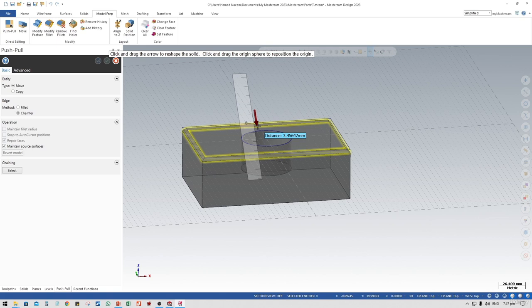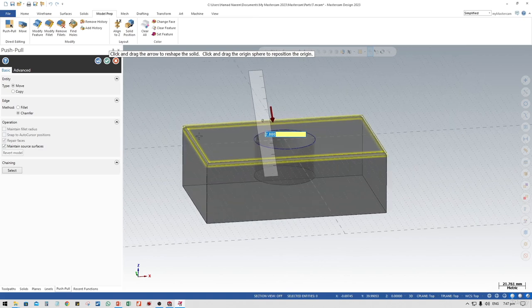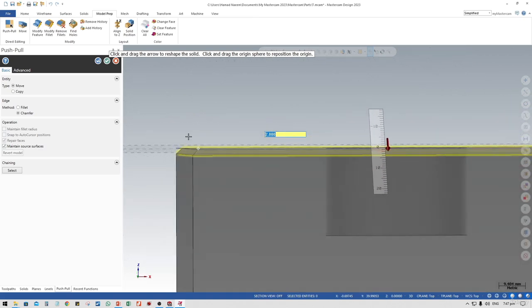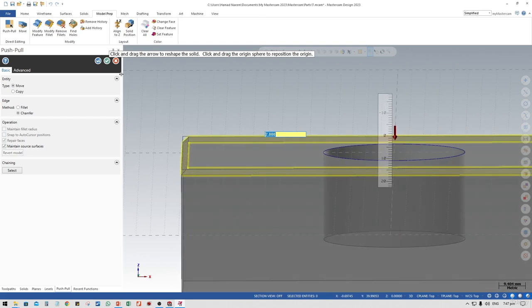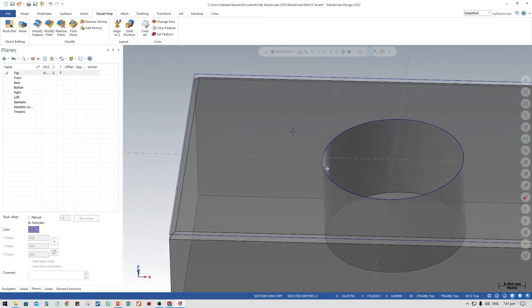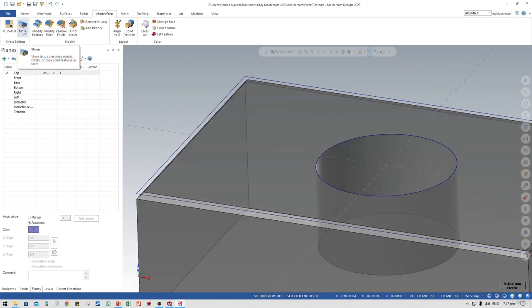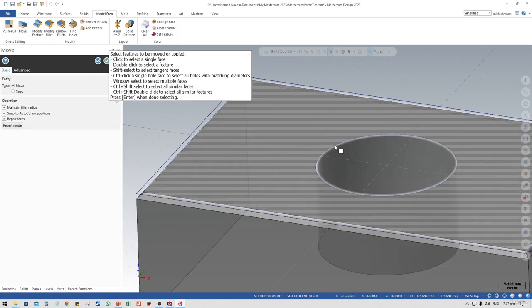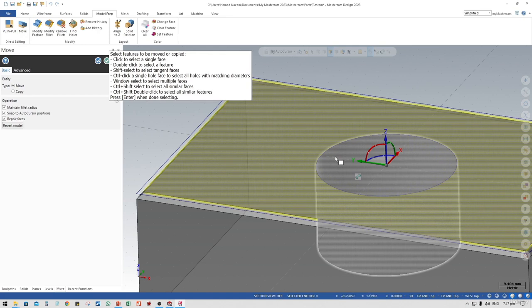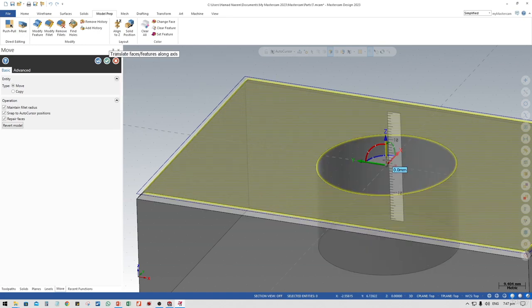It is very easy to create. I'm going to set 2.0, just write 2.0, and it will make a 2.0mm chamfer at an angle of 45 degrees easily. This is very helpful to create features like this. If we want to make it a little deeper, you can select this and make it a little deeper.